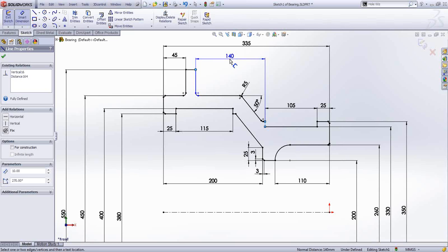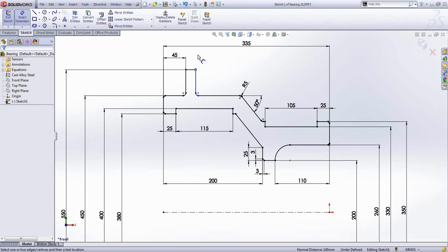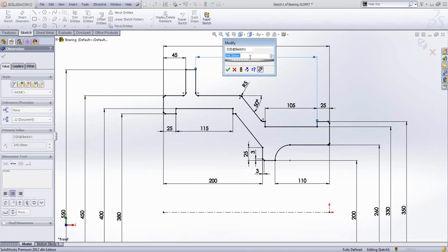But in SolidWorks 2012, you can hit escape and you notice that SolidWorks is retaining its first selection here. So now you don't have to pick the first reference again. Instead, you can go and pick the second reference which you were wrongly locating for the first time.